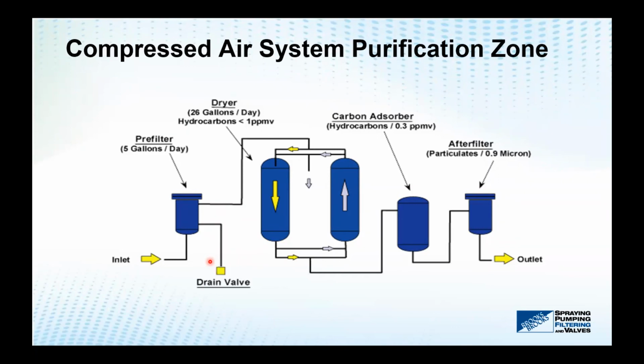In the summertime, it's very hot and humid. So the amount of liquid coming out of that drain valve changes quite drastically between seasons. And with new technology, it's almost a cost-effective upgrade to put no-loss drain valves that actually detect the amount of liquid in the sump or in the exhaust of where we have to drain that liquid.